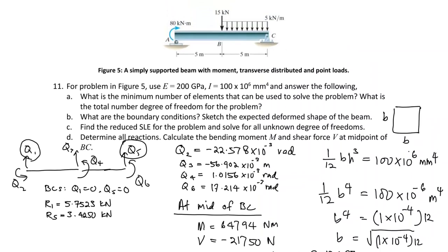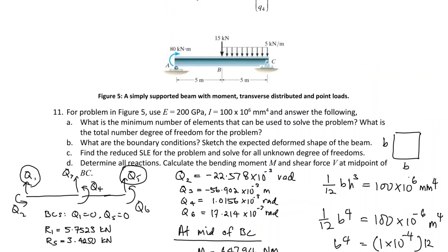But when we are doing finite element, I think we need to give more details to the software. In this case, when we have the load, the beam will deflect something like this, and there's a pin joint here. For a pin joint, because it is fixed, there's no delta x. It cannot move in the x direction.